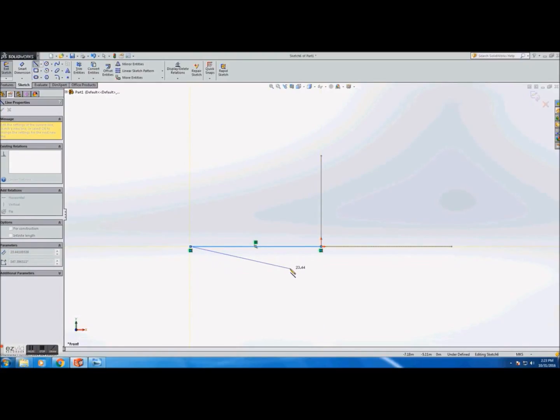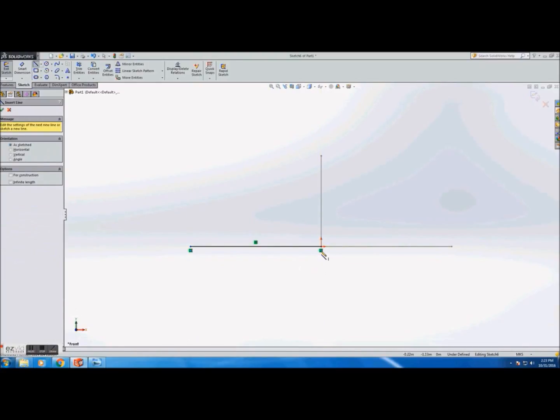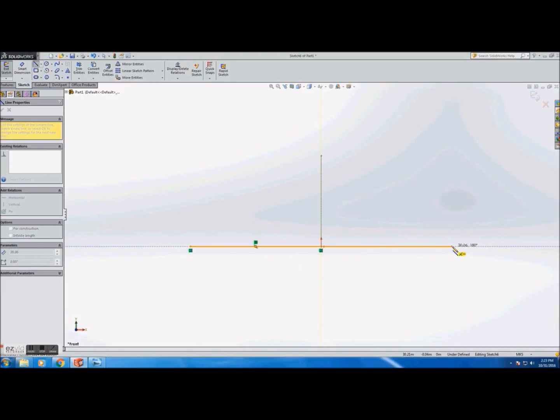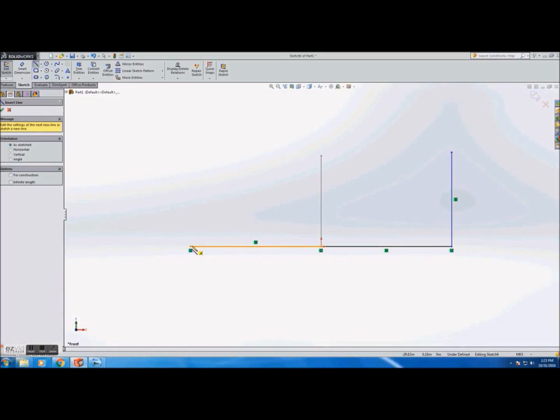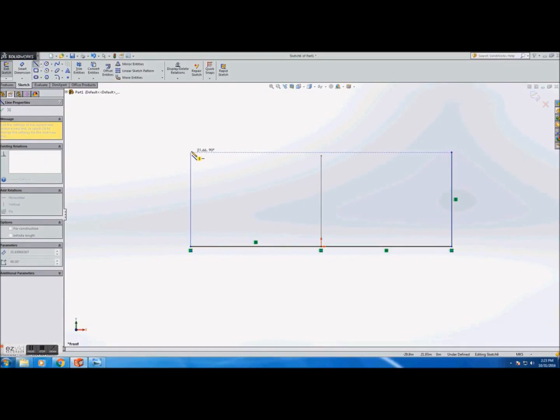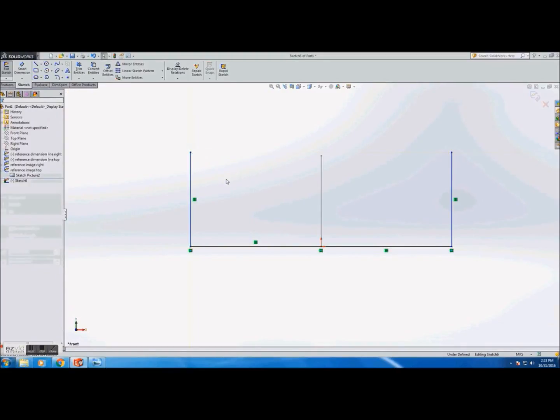As I said before, with regard to having lines available in different planes, you might need to go over the same lines again in some places to make sure that you can actually interact with these lines. What I'm doing in this particular case is creating the wing limits again, like I did for the wing box or the aircraft box in the top plane, just so we can line up our wingtips again with a reference point.